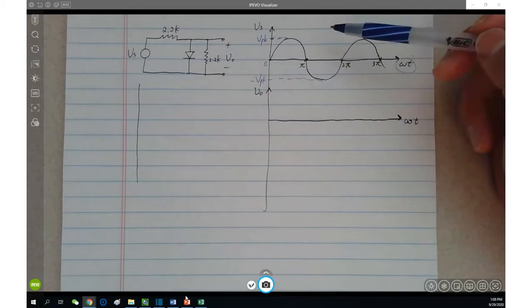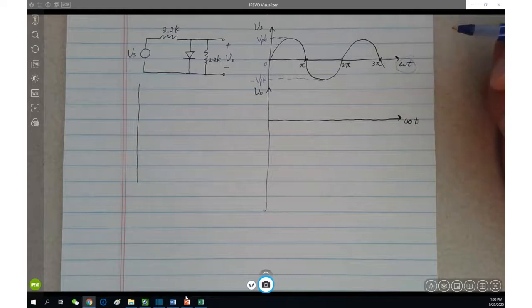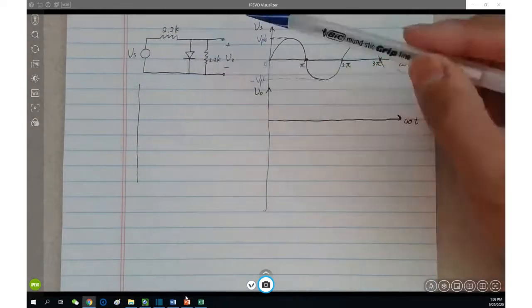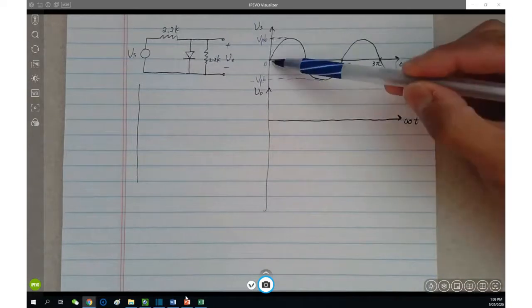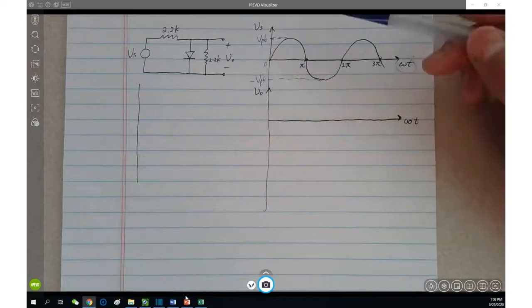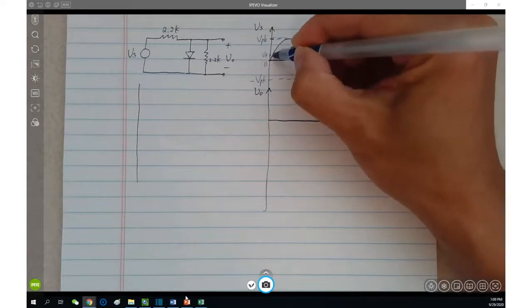However, let's say Vs is beyond V gamma. Is the diode going to be on? From off becomes on? Not enough, right? Why is that? When it's off, here is an open circuit, none. There are only two same resistors in the circuit. Then you gradually increase Vs, and what do you see? When it reaches V gamma here, say here is V gamma, is it going to be on?